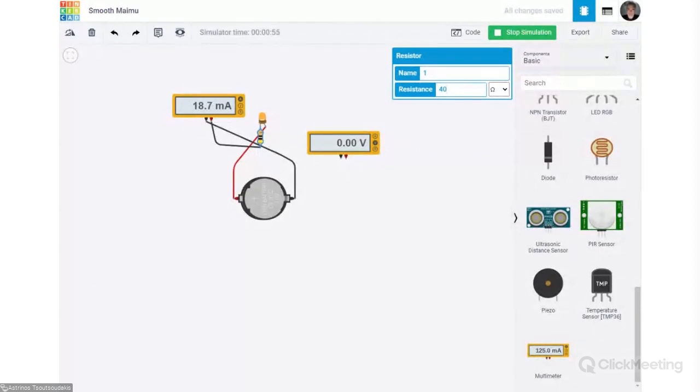You will find a list in my presentation of what you can buy. For example, in this range, you can have 30 ohms, 33 ohms, 36, 39, or 43. So we are going to use 43. It's very good, because this is what is available when you go to an electronics shop.